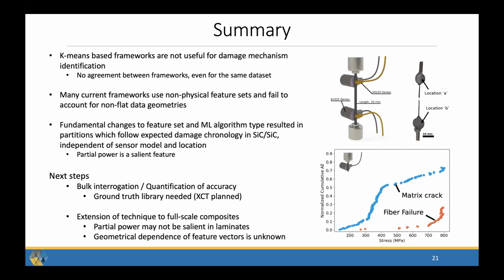No, I think partly because there's been a little work, but it changes so much in the entire composite. The break signal of a single fiber being tested is very different, because the experimental constraints have such an effect on it, than it will behave in an entire laid-up composite, because the processing is also different. The way a fiber is processed as part of a composite, with the weak fiber-matrix interface, and the way the signal behaves there, is very different.